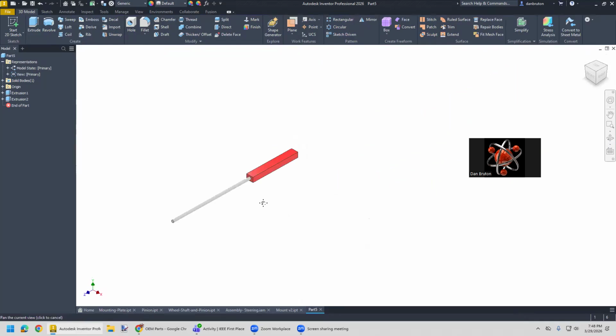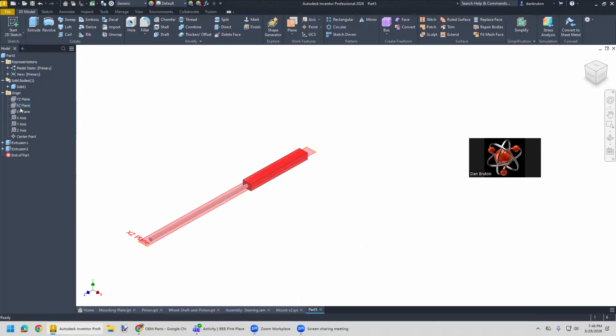It might be a bit much, but at least we get the idea of that. Okay, and then the rod ends go here. This is where it attaches to the knuckle. Should we try to do a mirror image for the other one instead of having to make it again? Why not? So if we look at the bisecting plane, it would be this one. We can right click and say visible just for a moment. You can see it goes right through the middle.